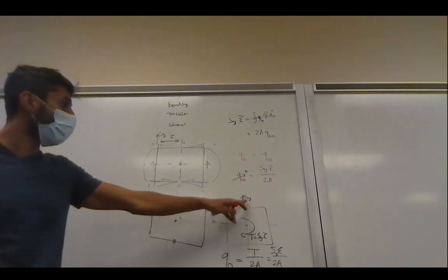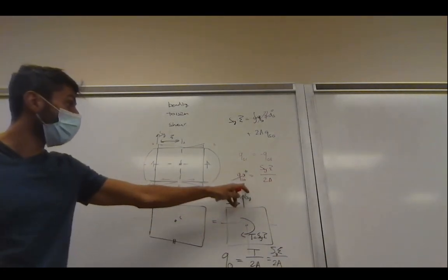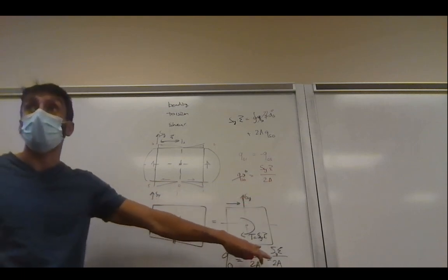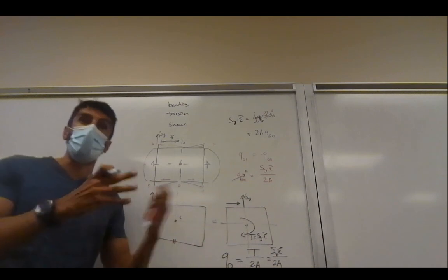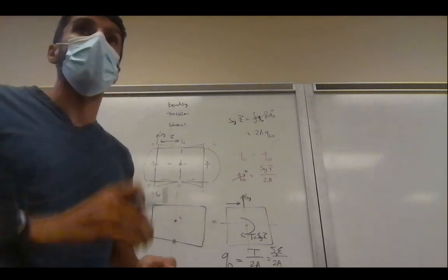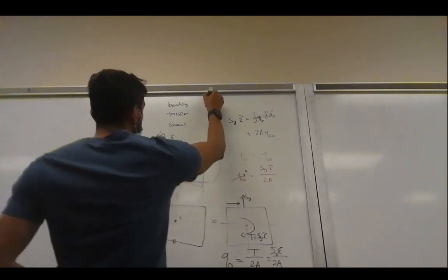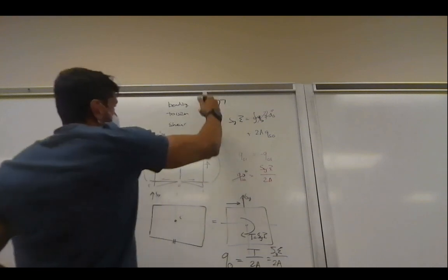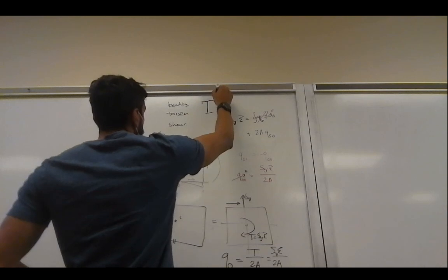we can argue that this equation, the correction shear flow, by just looking at the shear force, would be automatically 0. We can see that from the structure. And we did an example in the class as well. I think there was one of the examples that we did that had a closed section, basically like a t-shirt, and you had an Sy acting in the middle.